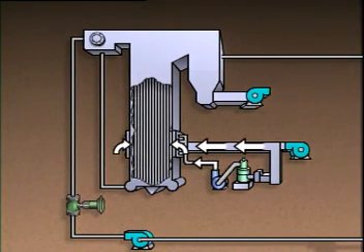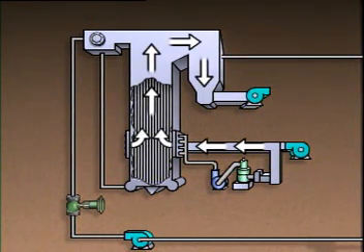After it has been determined that a boiler flameout has occurred, the next step is to put the plant in a safe condition. The real danger with the flameout is that a combustible mixture of fuel and air can collect in the boiler because fuel and combustion air are still being fed into the furnace. If the operator simply relights the burners, the boiler could explode. In this case, to make the plant safe, you must first stop the flow of fuel into the boiler. Then you have to get rid of all the unburned fuel before relighting the burners. This is done by using the airflow through the furnace to blow the fuel out, an operation called purging.